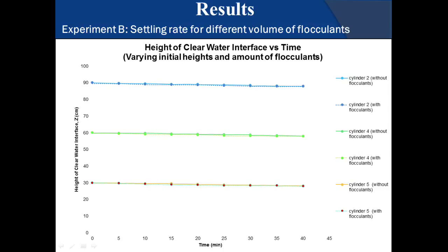This supports the theory. The function of flocculants is to bring together coagulated particles into larger aggregates and settle them. Flocculation occurs after the addition of chemical to destabilize the charges on the colloidal particles in suspension. These charged ions provide an opportunity for the charged particles in a system to adhere to them, thereby merging individual particles that are larger and heavier. Hence, the settling rate will be greater.